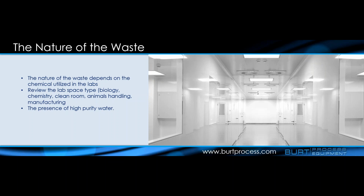Chemistry, clean room, animal handling, semiconductors. All those things tend to have certain waste characteristics that you might want to account for that could come up down the road. For example, in pharmaceuticals, you're going to see a lot of CIP, which is called clean-in-place chemistry: potassium hydroxide, phosphoric acid. Semiconductors, you might see a lot of high acids, things like hydrochloric acid, possibly HF, which may need to be accounted for, deionized water.